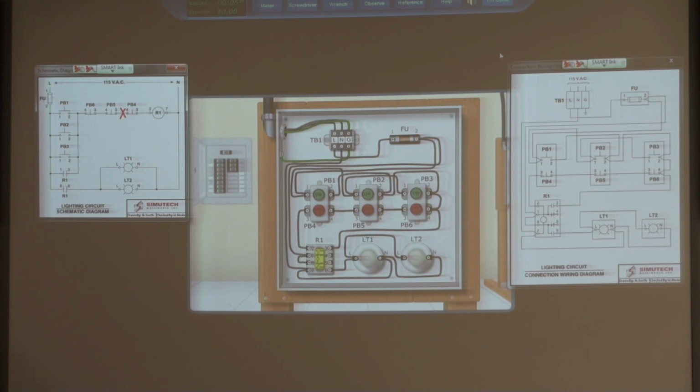You said that wire breaks. If it breaks, the coil will not energize and the relay will not engage. The lights won't come on. Well, they were already on, so what happens as soon as that wire breaks? They go off. They're going to go off because the contacts are going to open.